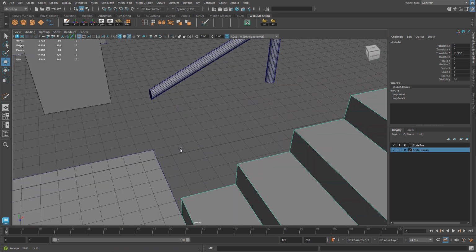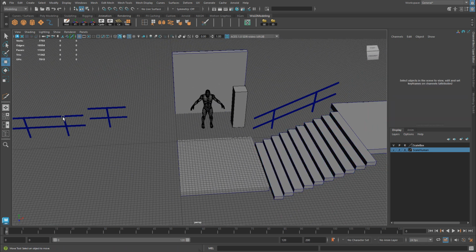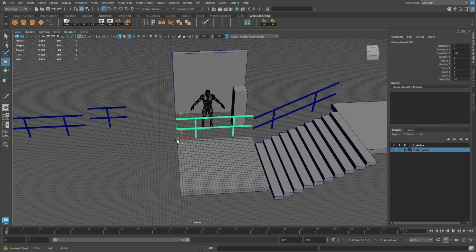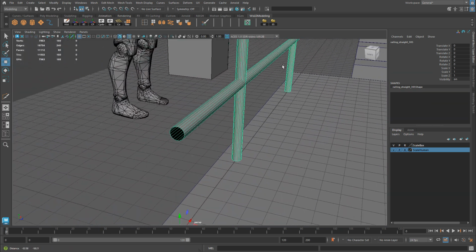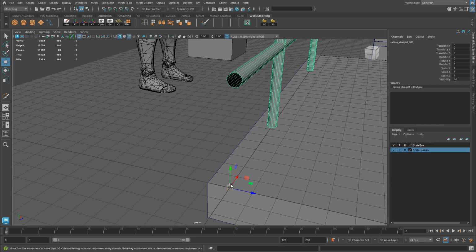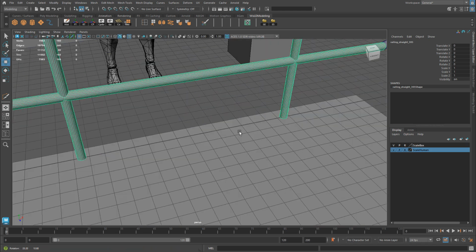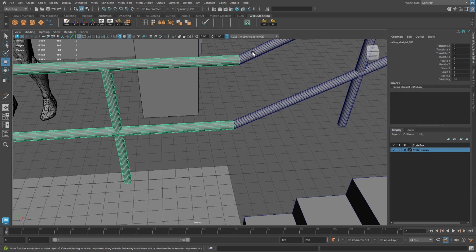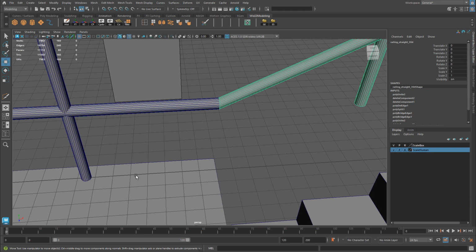So essentially it would be, let me reintroduce this piece. Control D temporarily so I can snap it and just judge exactly where it would be. So the pivot point for the straight railing is right here on the bottom and on the grid. And then when it aligns flush with this, we need a pivot point to be along the same line. So both of these can be put together and they are seamless next to each other. So I'm going to hold down D, X, and snap my pivot point right there.